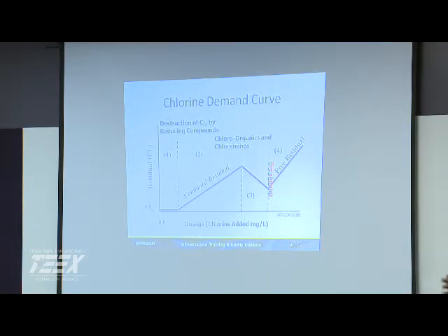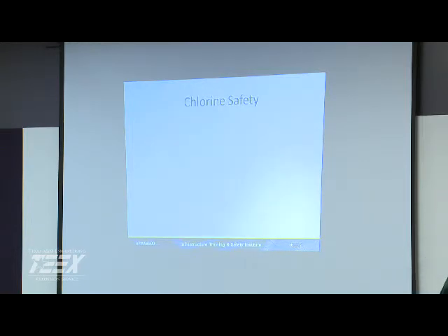So that's a really important concept depending on what type of system you're running. If you're using chloramines and things like that, you want to make sure you fall in a certain range. If you're having taste and odor issues, see what your feed rates are, see what your residuals are, make some adjustments and see how it's affecting things. So, Class B and Class A operators, Bs, you have to be able to draw this out and label it. Class A, you've got to do an actual summary of it, a little essay. But it's a real important component of our treatment.